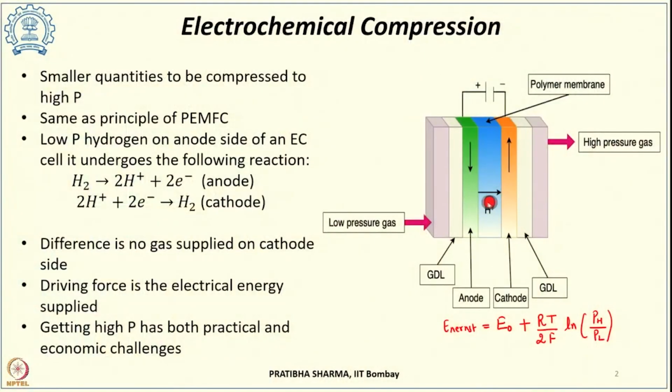Secondly, if we further increase the pressure, the permeation of hydrogen from the cathode side onto the anode side, the process known as back diffusion, will also increase. To address back diffusion, the membrane can be made thicker. But if the membrane is thickened, the membrane resistance will also increase, and as such ohmic losses will increase, and finally the efficiency will decrease.